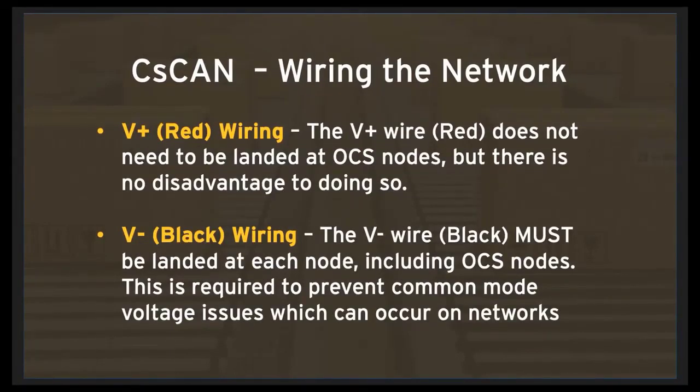Let's talk a little bit about V+. Now remember, V+ is required if you are going to be powering a node from the network. So if you're talking about an OCS, whether that's a microseries product or an OCS, let's say an XL4 or an XL7, there's no requirement for the V+ to be landed on the terminal block for an XL7, XL4, etc., any OCS for that matter, because it's not actually using that terminal for itself. However, there's absolutely no disadvantage or harm in connecting V+ to the terminal strip. And I would recommend you go ahead and do it.